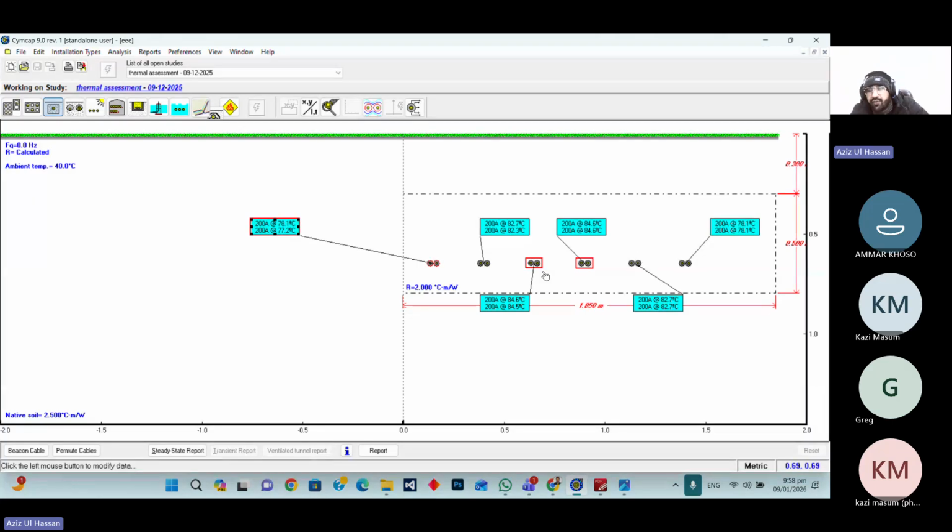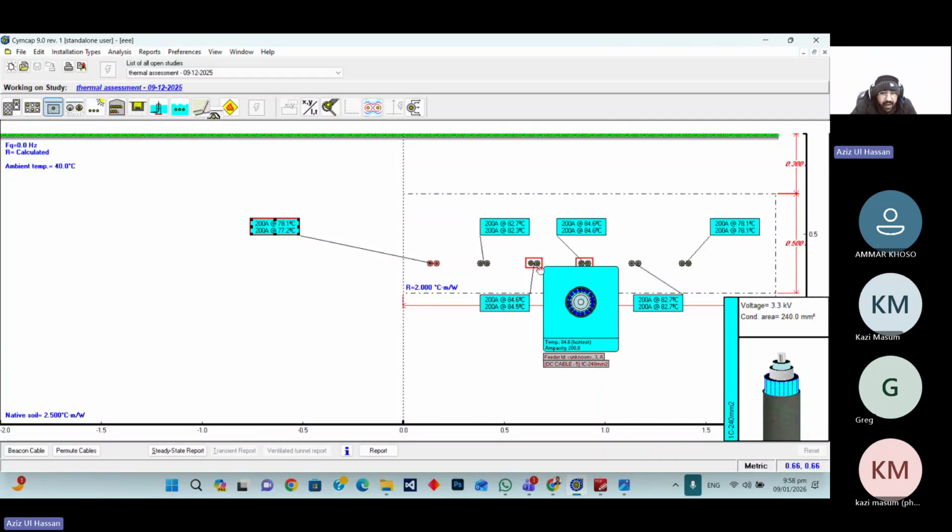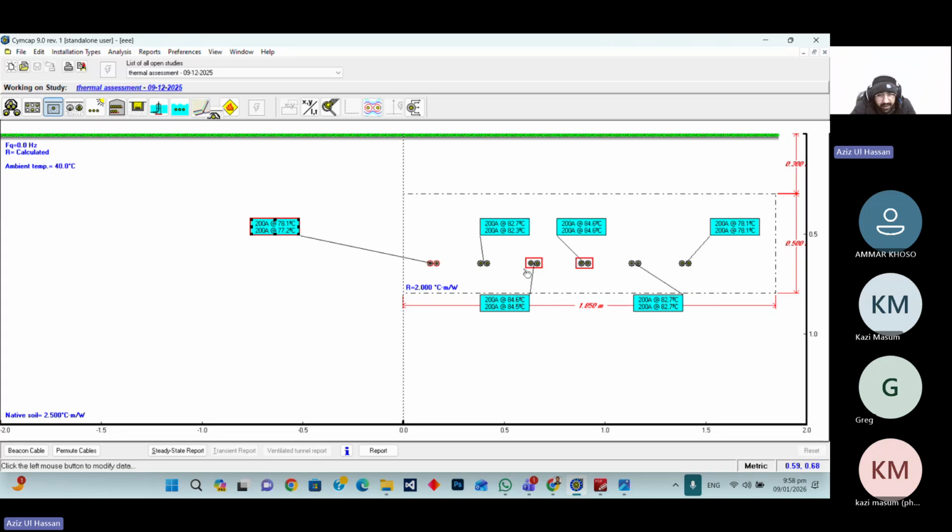But in our case, we are using double runs of cables. In the DC cables, we are basically using double runs of the cable. That is why you see 200 ampere, 200 ampere for each. The software does not automatically divide that. I have just given them the divided load. I have 400 ampere load current, and I have divided it between the two. So this is the study.